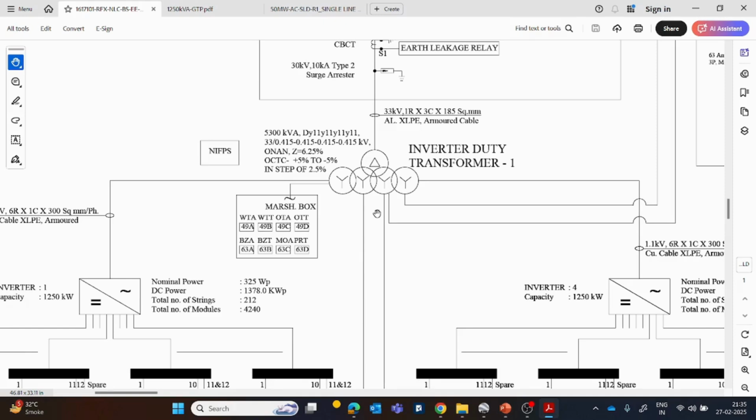Second, in a plant you consider design margin for the future, and also because the same transformer is operational year on year for 20, 30, 40 years, so it gradually degrades. I won't say it degrades immediately, because a transformer doesn't degrade quickly.